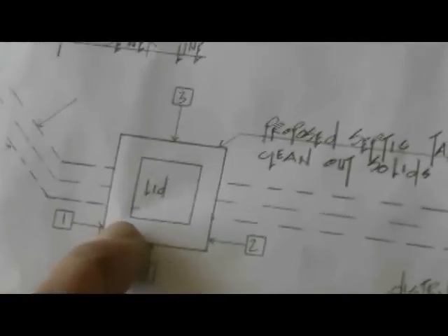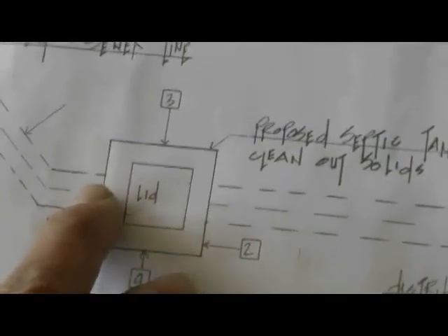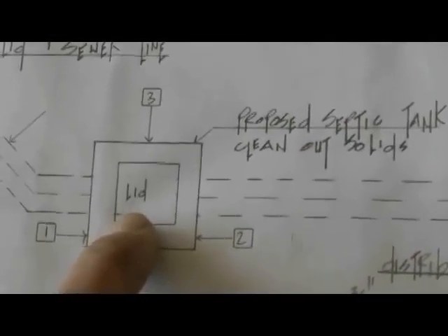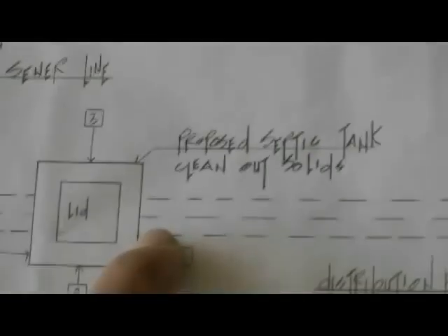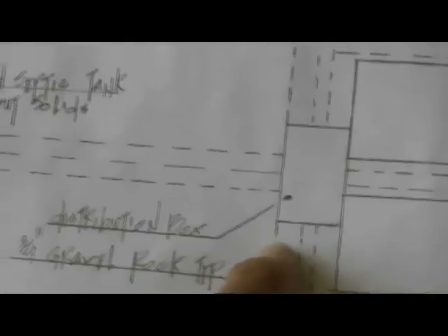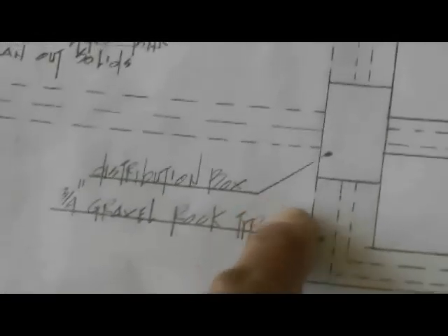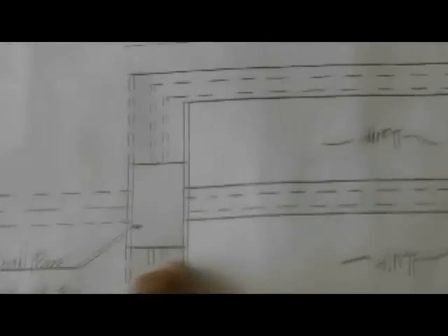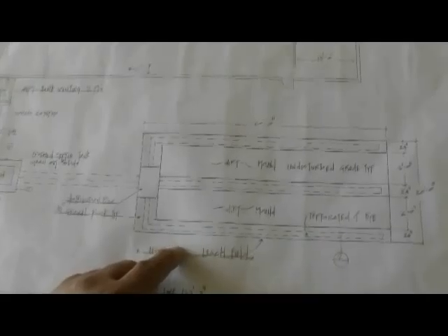Now, after the main septic tank for the cleanout is built, the lines are going to continue as a solid line, and then they're going to go into what we call the distribution center or box. There's 3 outlets here, here, and here. If I zoom out now to the whole layout of the leach field, you'll see that it's 50 feet long by 20 feet wide.